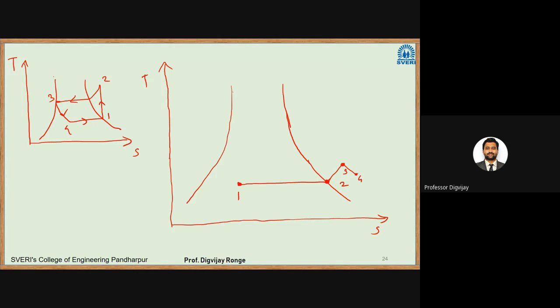Then when that refrigerant comes in contact with the cylinder walls of the compressor, if it is a reciprocating compressor, when the superheated refrigerant comes in contact with the hot walls of the compressor, again there is a rise in the temperature. So this is the fifth point. Now there is a compression process. Previously it was an isentropic compression, but in actual it is not the case. So this compression will take place like this. So that compression has now finished.